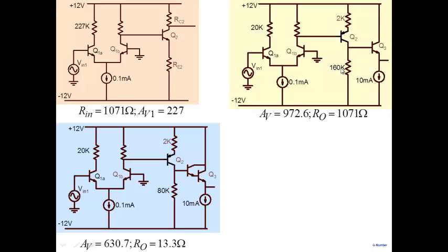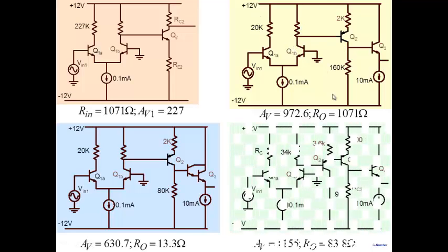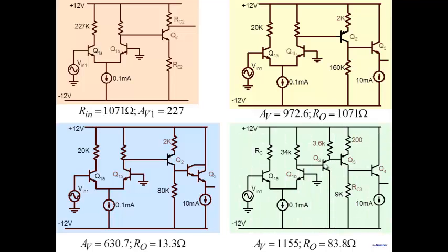And we said this resistor is high because I want this resistor to be reasonable to avoid the loading of the previous stage here. So one way of avoiding the whole thing is you add another stage, a common collector stage here, which prevents the loading of the differential pair by the gain stage here. And then this allows you to reduce this particular resistor. From 160K, you can get it to 9K. Note that we reduce this resistor and we reduce this resistor as well.